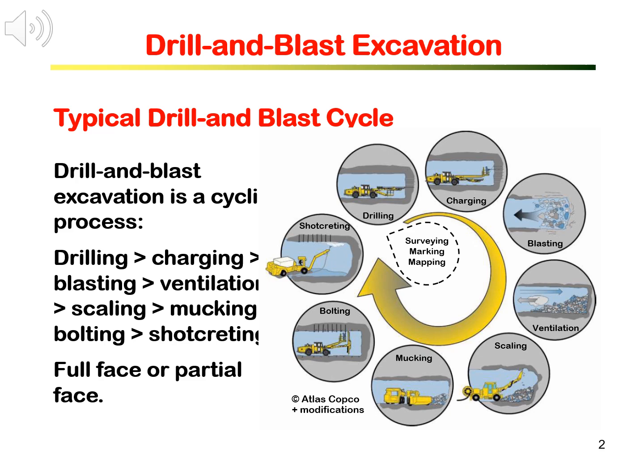Often we will need to make sure the excavation working area is safe by installing temporary rock support using bolting and shotcreting. If drilling is not computerized, we will need to mark the positions of the holes on the excavation face manually. If we want to do joint mapping on the face, then this is done before drilling.